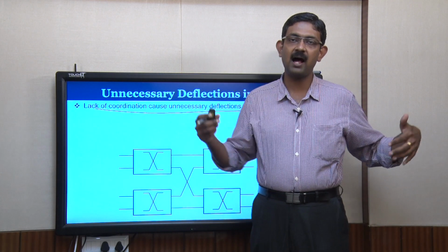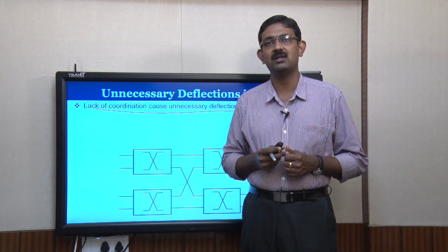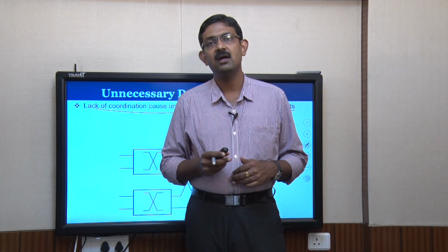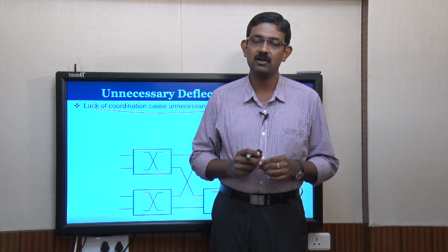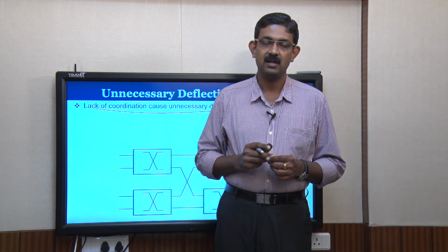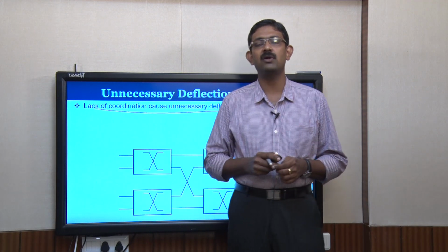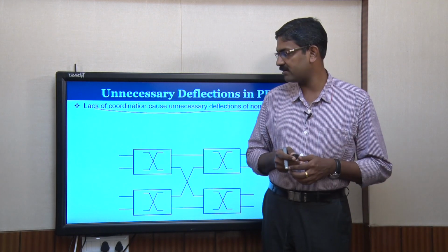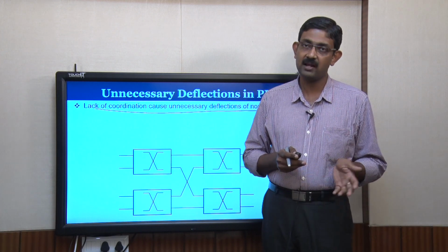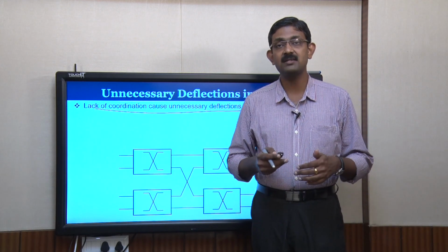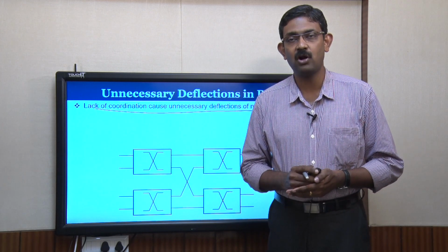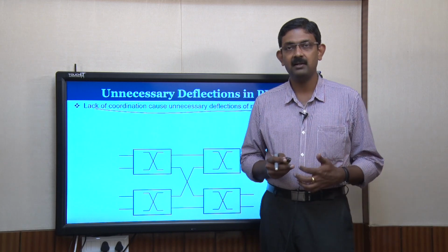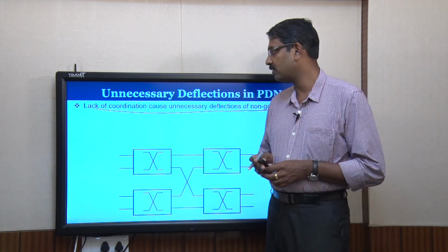So, if you consider a large NoC setup with multiple routers, only one of the routers is going to handle the golden flit and all the other routers are going to deal with non-golden flits. And regarding the prioritization of non-golden flits, only one flit will be chosen at random. So, in the arbiters, one of the flits is chosen at random and that may get priority. So, the issue is that the majority of the routers are handling non-golden flits. So, there needs to be some kind of improvement in handling these non-golden flits.